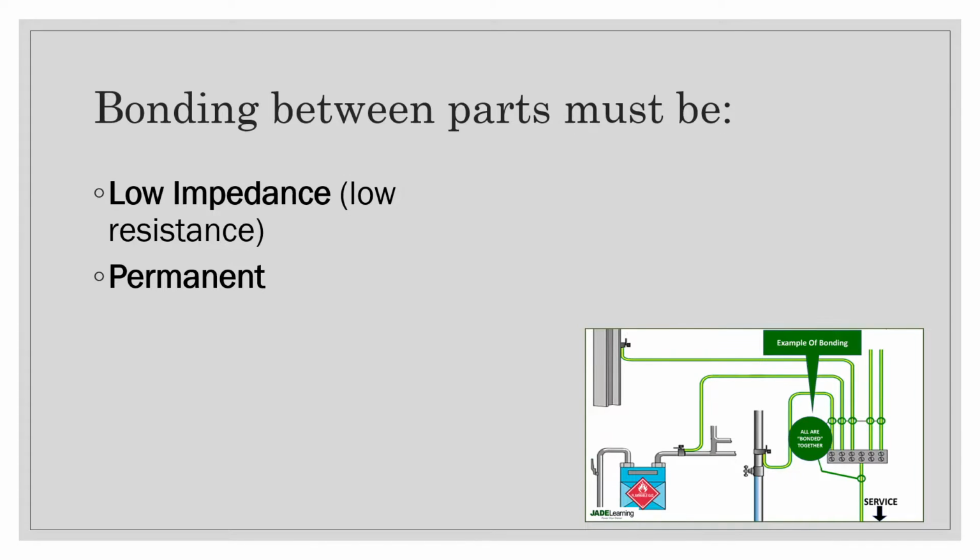And this is sort of related. I know we've talked about in the past about EMT. You don't have to run a bond connector through an EMT, because the EMT, being metallic, can act as your pathway of any sort of fault current that may occur.